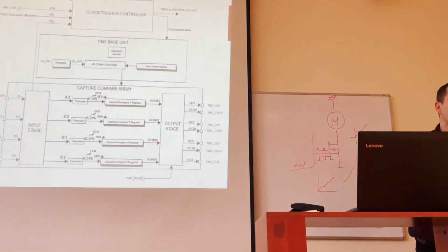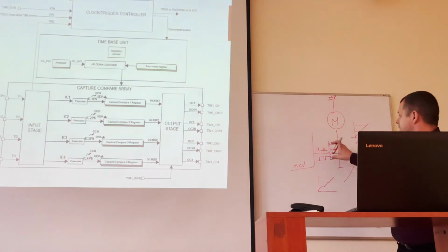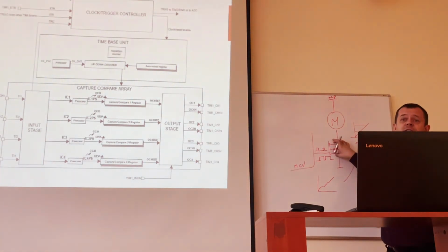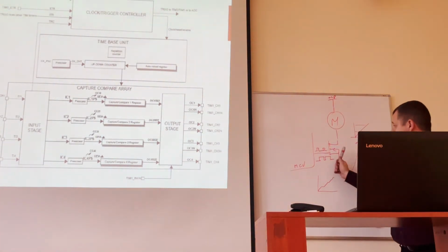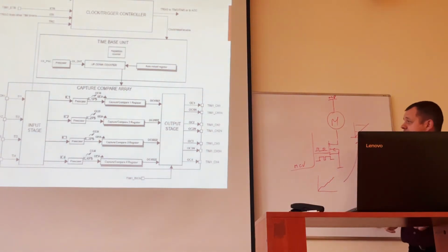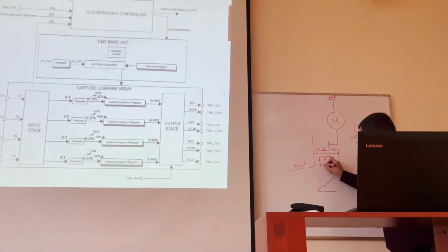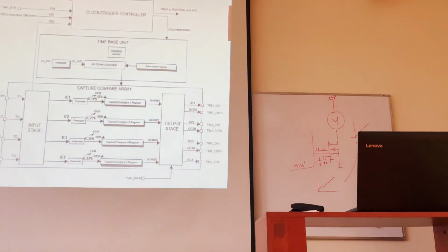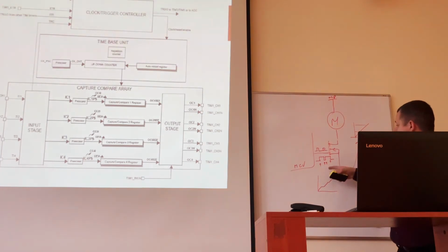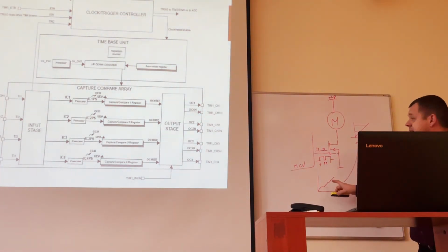It will dissipate a lot of power. Because with the transistor in the active mode there will be huge heat dissipation, huge heat loss on the transistor, and the transistor will very often simply evaporate. With switching on and off, of course, there are also power losses during switching, but only during switching. When the transistor is fully on or off we don't lose power, because either there is no current or the transistor has very low resistance, so we lose much less power than in linear control.